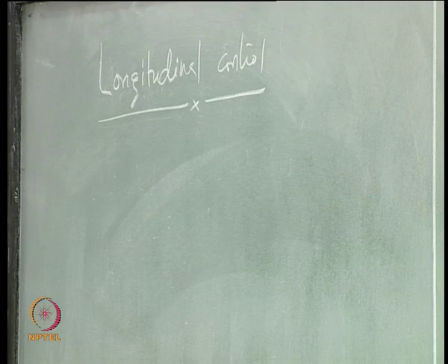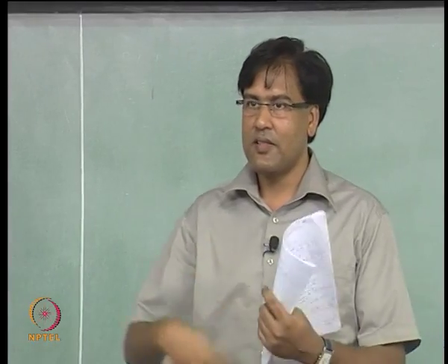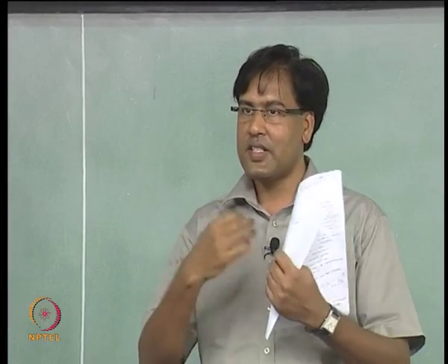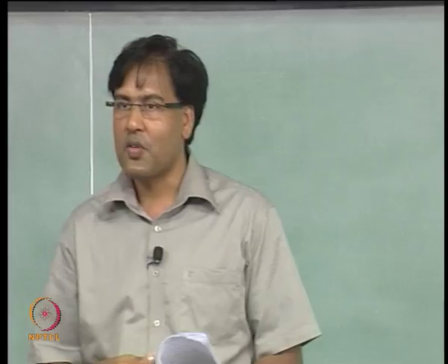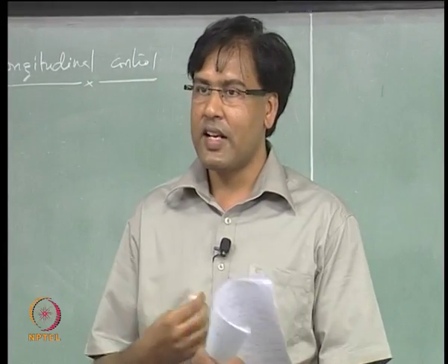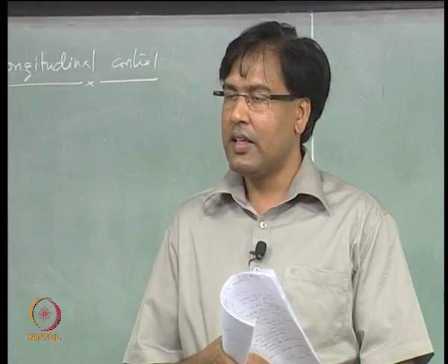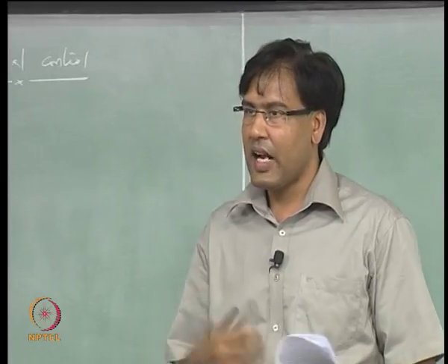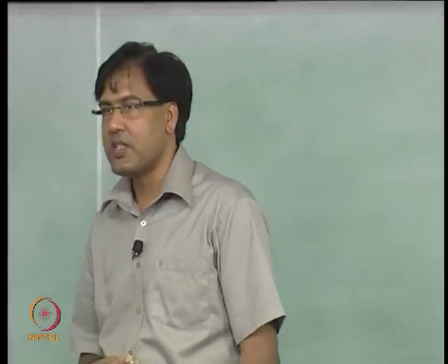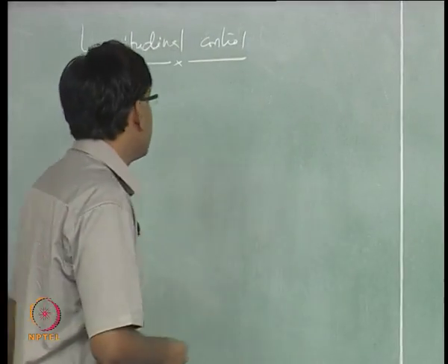Okay. So, we said that there is one situation where the elevator is free to rotate, right, that means the stick force is not required to change the elevator deflection, and that free deflection of the elevator can be found out by setting the hinge moment to 0, isn't it?